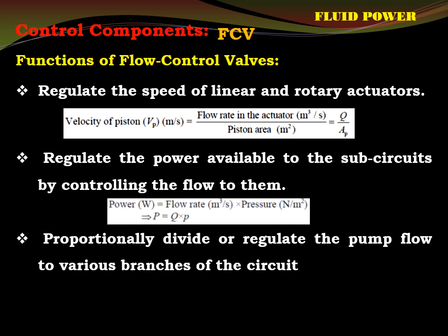They can control which part of the circuit requires what amount, and it should be controlled, because if those branches are left unrestricted, then branch circuits may receive an oversupply of fluid, which in turn can operate them at greater speed than the specified, required one.